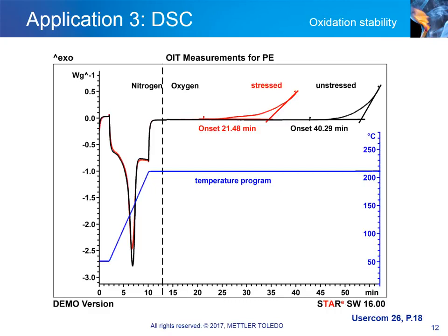The method is frequently used to study the influence of antioxidants or other stabilizers on the stability of a material. In the absence of any additives, information can be obtained on comparative molecular weights. The larger the OIT value, the higher the molecular weight.